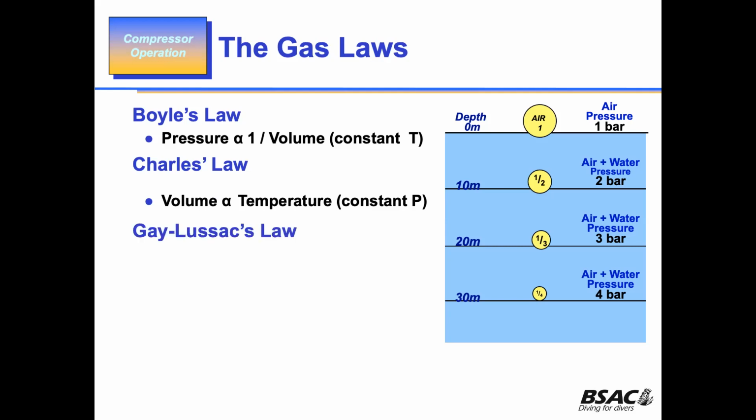And the last one is Gay-Lussac's law, and that says pressure is proportional to temperature, providing the volume stays constant. The reason you need those other 2 along with Boyle's law is because in compression and filling, both those other 2 laws come into play. So you need to be able to understand what they are.